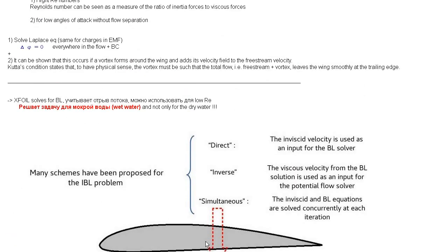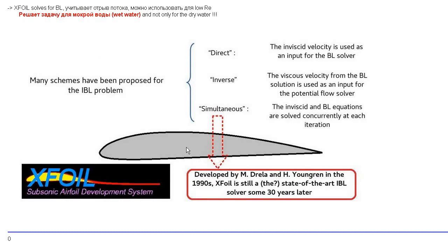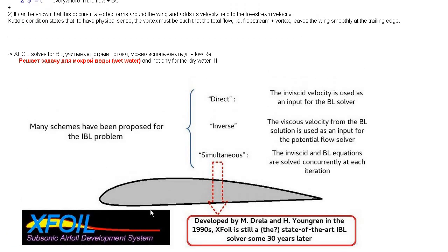So the XFOIL software does this beautiful job for us, and we have the solution. And we also can write a script to simulate plenty of different airfoils at once without the necessity to enter them manually. And we will see it in a moment.